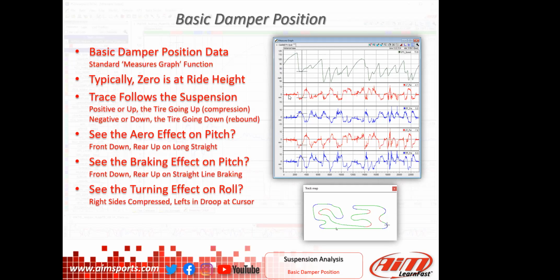And as it's getting closer and closer to up to speed, getting above 112, 113 miles per hour, you can see that tire is going up into the wheel well, or the nose of the car is being pushed down, right? You can see it especially here on the right front. It started here and it's being pushed down to nearly zero just before he hits the brakes. That means the car was nose high as it was coming down, and as it was slowly going down the straightaway, the nose was coming down.